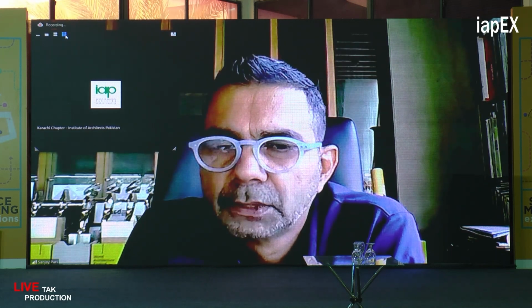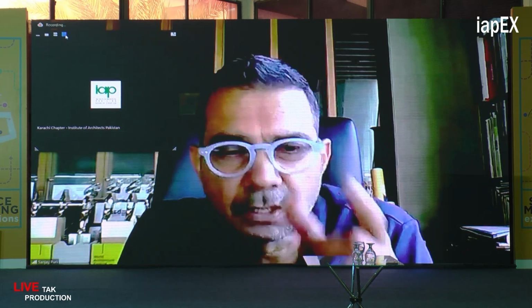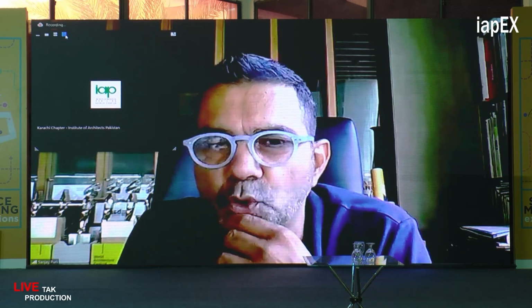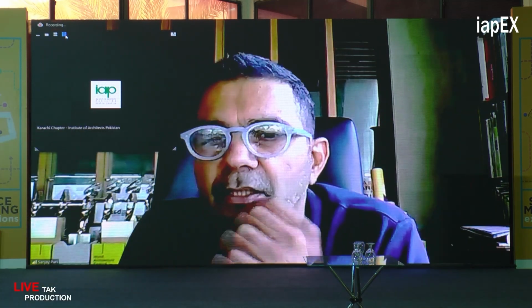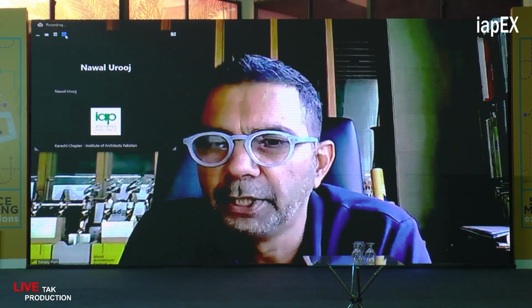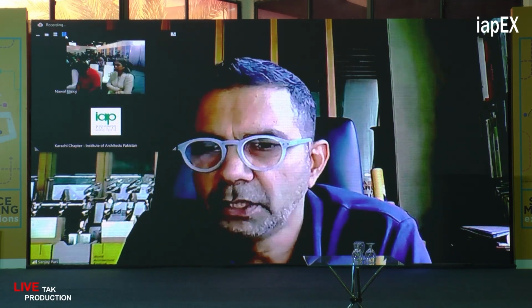So I would like to just hear your feedback on that. Thank you. Yeah, so the envelope, as we say, whether it's in the form of a stone screen or just in the arched house or sheltered arcade, has basically come from reducing the heat gain and creating an interstitial space. It comes from there. Otherwise, you can do a window and you can do a large overhang.